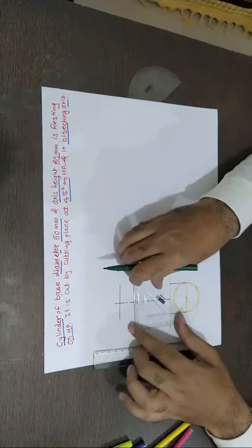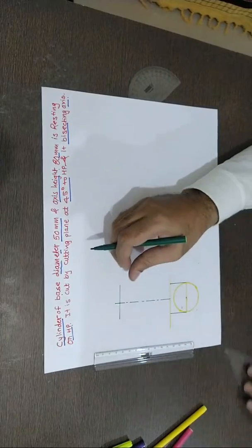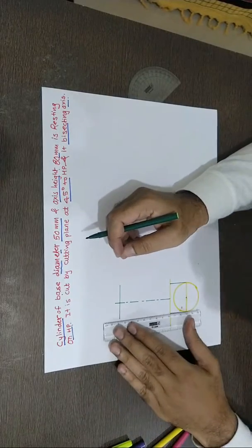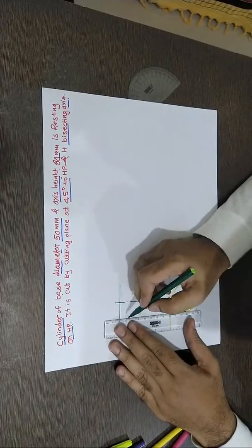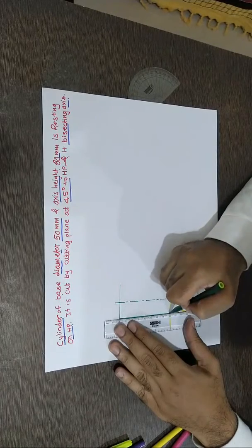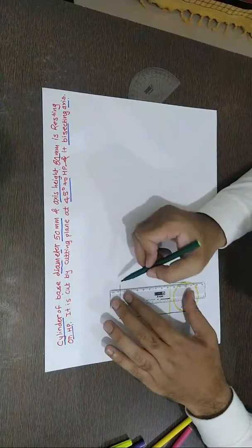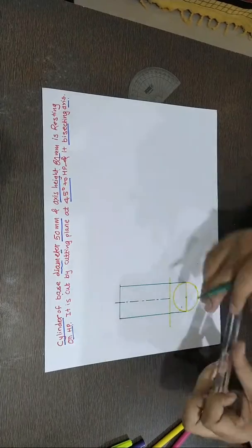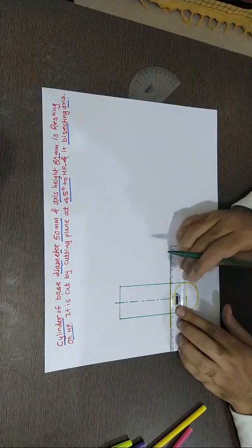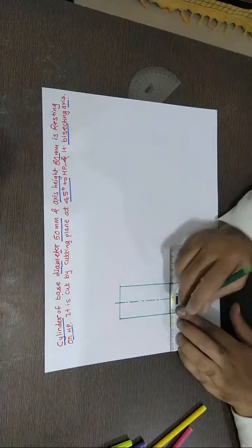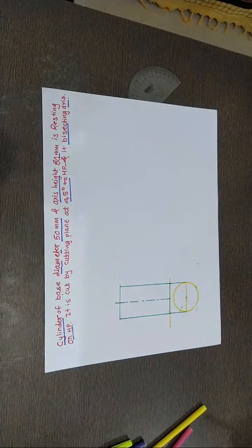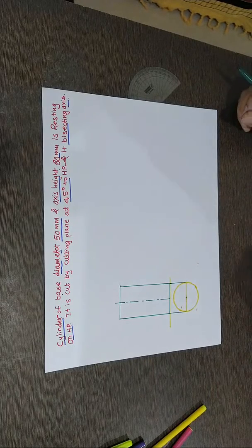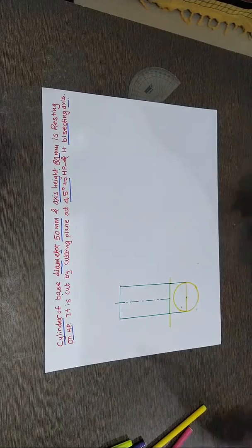See, you can draw very fast with all the instruments and the pencil or with the drafter. Here I am just ensuring a conceptual procedure and the concepts so that it's quite easy for you to understand it when you are drawing. Fine. So this is the front view and the top view for the cylinder of given dimension, 50 mm diameter and axis height 80.